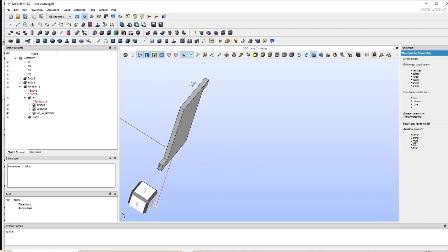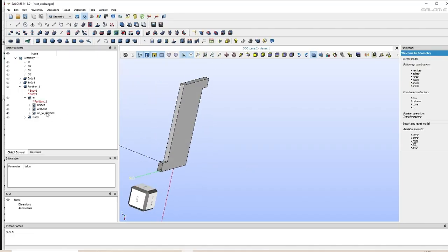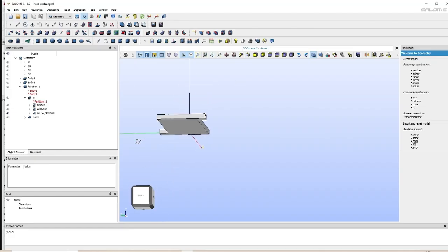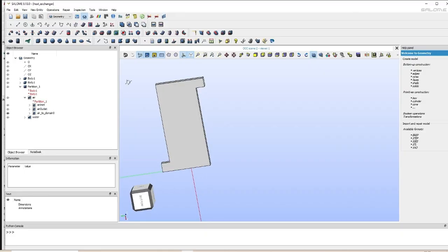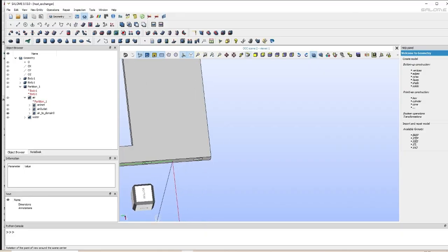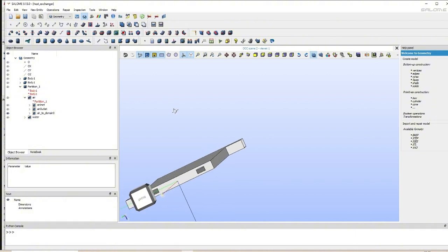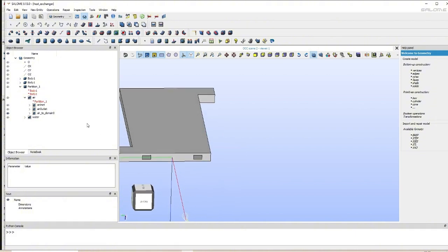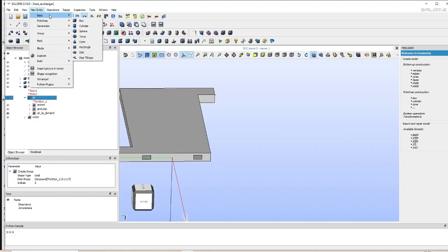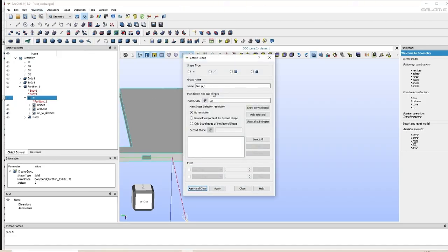So if you want to show, you can see if it's correct. So now it's air to domain 0. It's mostly the walls only without inlet and outlet, and also internally it has no water to air interface. So that we are going to do next. So how to do that? I will just create a new entity group, which is faces still, but now I use all faces, all air faces.